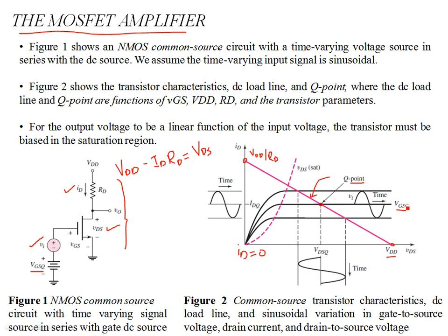For this variable VGS, you start with the non-sat region, which is the ohmic region, and then once you pass beyond the VDS sat, which is given by the overdrive voltage, VGS minus the threshold voltage. Threshold voltage for a given transistor is constant, given the other parameters like temperature or the bulk effects are not taken into consideration. So VTN is constant. But if you go on increasing this DC VGSQ, your Q point is shifting, right? Which means the VDS sat is going to shift towards the right.